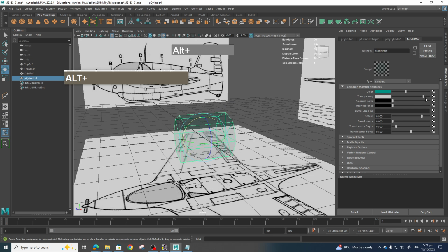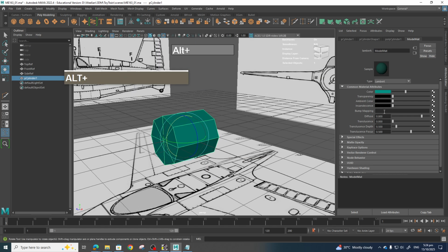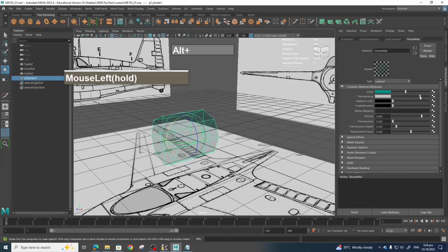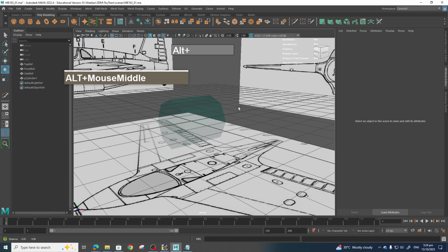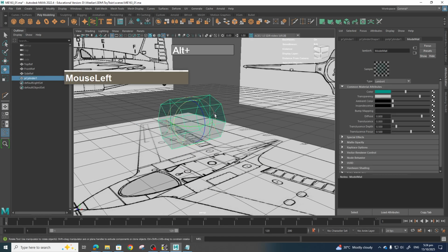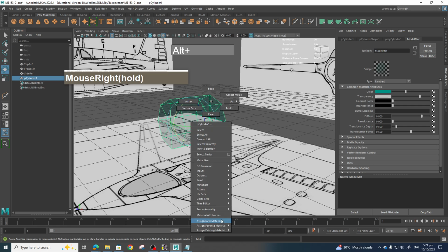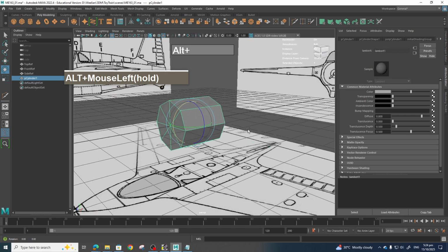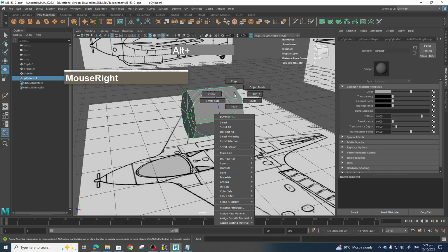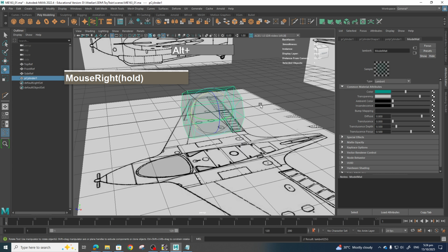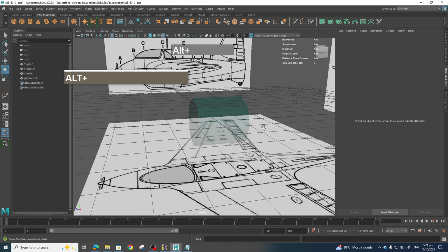So if I want it to be solid again, unfortunately, I have to switch back to solid material here. But one thing you can do is go into this transparent material. If you want to switch back to your solid material again, you can right mouse click on it and then assign existing material Lambert 1, and then you'll be solid again. So if you want to look through it, right mouse click on it, assign existing material, model matte, and then you'll be transparent again. Okay, so right now I'm in this transparent material.